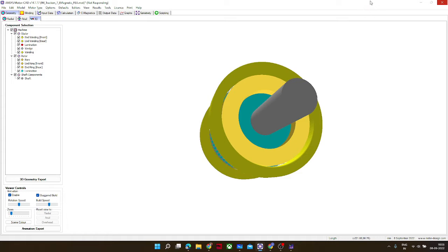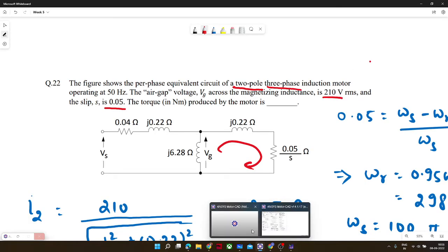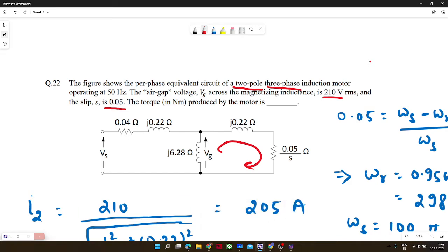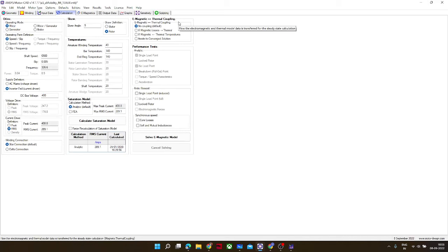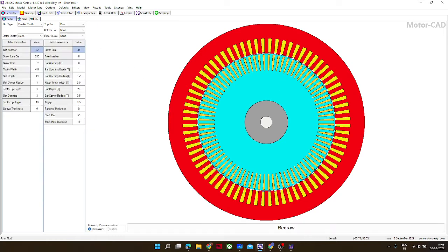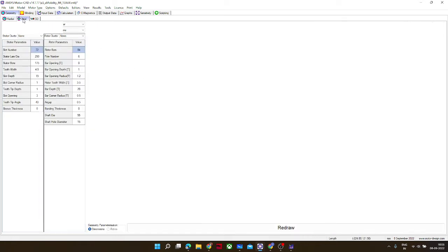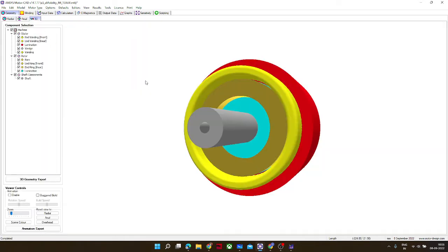So the higher the rotor resistance, the higher the power. But one side effect is that with higher resistance you will get higher losses. That's why the induction motor is generally considered a less efficient motor, and that's why people moved ahead with advanced permanent magnet synchronous motors also. To generate torque, you can see the cages here.